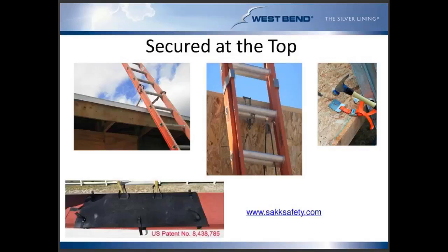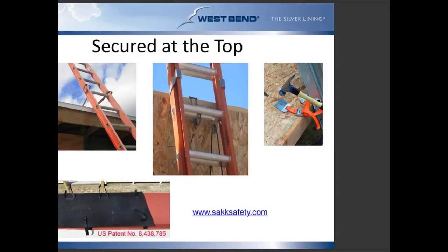And the reason I like this is because the metal flashing on the top of that, the cap of that parapet wall, is oftentimes slippery, especially during the late winter and early spring months, where we have the thaw and refreeze. So this is a slip-resistant mat that, as we're making that transition from ladder to parapet wall, provides better traction when doing so. So the link is there if you want more information on that, but just an interesting solution. But nonetheless, we need to secure those ladders to make sure that they're not being displaced as we're climbing them.